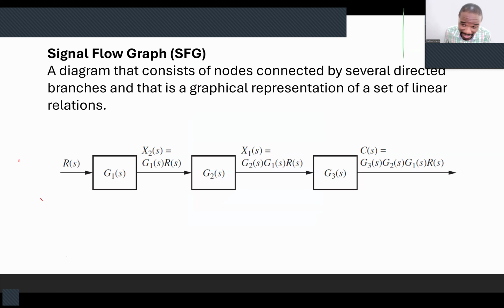You only apply it. Once you see this S, you know that we have changed something from one domain to the Laplace domain. That's why there's an S there. It has become a function of S. Is that okay? So that's a transfer function. Now, your output is usually a product of your input times what your controller is doing. Your controller is doing something to the input. It will multiply it, it will act on it so that it has an output.